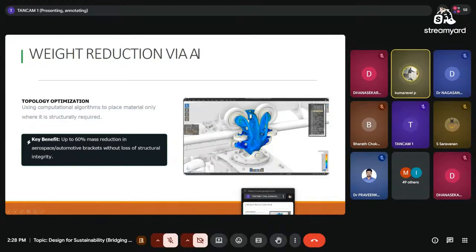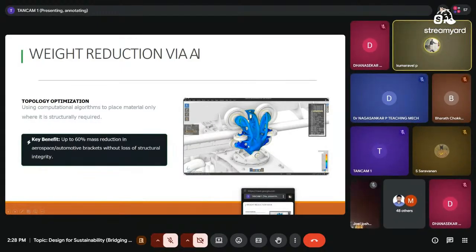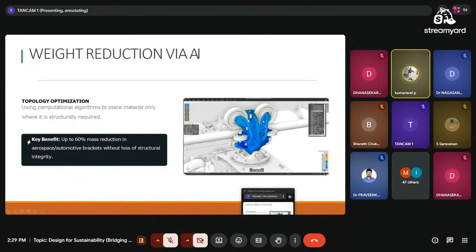See here what we are doing: there is a shaft and there are two rollers here. At the bottom there are two rollers, and on the side two rollers will be there. We have to connect these rollers with this shaft so that it slides along the shaft. That is what we are going to do. At the initial stage, a rod-like shape will be here, connected with all the rollers. If you place a rod here, it will have much higher weight, so the component weight will be higher, creating a lot of weight-related problems, right? So see what I'm doing here: instead of a rod, I create a simple line-like structure with a support inside it, so that it provides the same support but with less material.